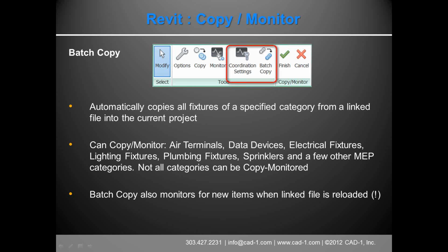And if we have time, we should have time, I might have to go through this quickly, but I'll try and cover this towards the end. Some of the things you can copy monitor using the batch copy: air terminals, data devices, lighting fixtures, electrical fixtures, plumbing fixtures, sprinklers, and a few other categories, but not every single category.